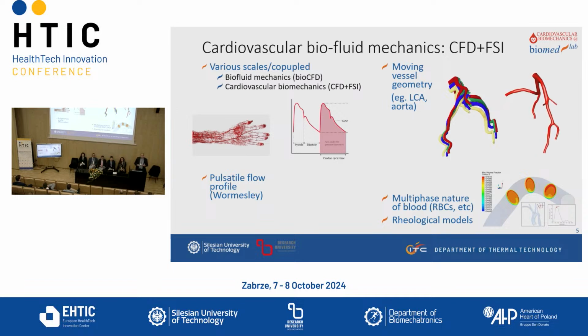We need to remember that the flow, due to our heart functionality, is pulsatile flow, which means that we always need to deal with a transient state. So we cannot perform the simulation in steady state, which provides some additional difficulties. We also need to limit our simulation to a limited time, which in some cases, where the geometry and the model are very large and consider a lot of numerical equations or numerical cells, is time consuming and challenging.